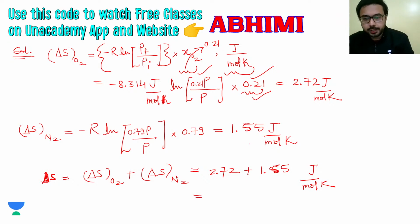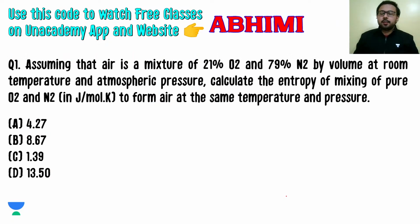So 4.26 or 27 is coming out to be the value in joule per mole Kelvin, which is the change in entropy, or the entropy of mixing of pure oxygen and nitrogen, to form air at the same pressure and temperature as given for the individual gases before they were mixed.